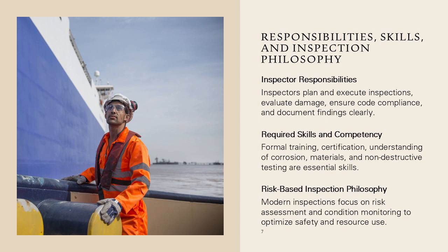aligned with operational realities. Competency requirements typically include formal training, relevant experience, and certification such as API 510 for pressure vessel inspectors. In addition to code knowledge, inspectors must understand process conditions, corrosion mechanisms, materials behavior, and non-destructive examination techniques. Sound judgment is essential, particularly when evaluating borderline conditions, unusual damage patterns, or conflicting data.